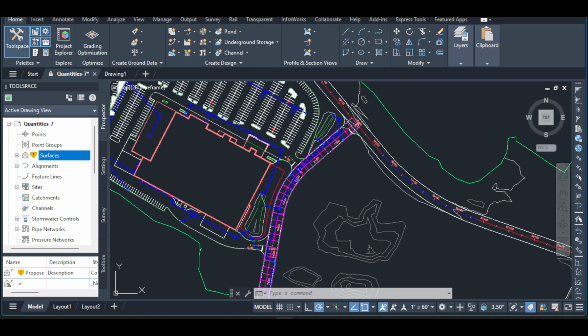In today's video, I'm going to teach you how to create a Civil 3D surface. By the end, you'll understand how to open the right palette, create a TIN surface, add the data that defines it, and generate the surface so you can review it confidently.